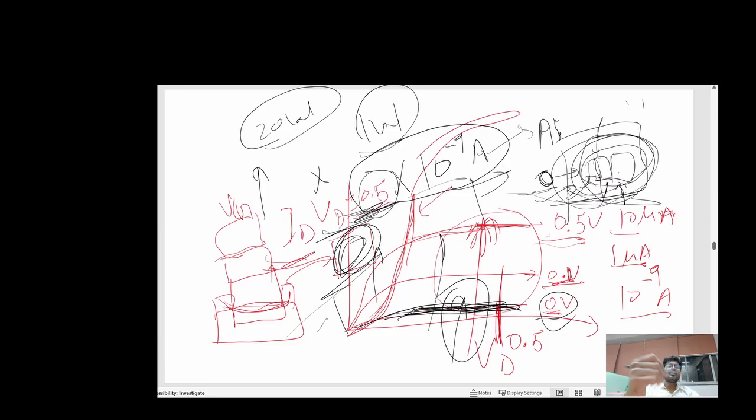Let us say you have 600 pixels in a screen, that is a very small screen, so 600 multiplied by 600. How many pixels depends on your screen, maybe megapixels. That many pixels with that off state current and the drain voltage applied gives the off state power consumption. So that off state power consumption should be very, very less.